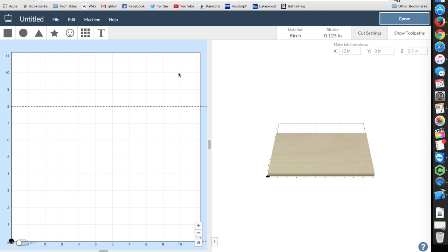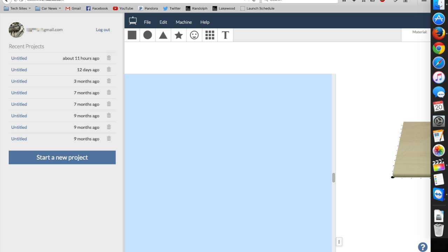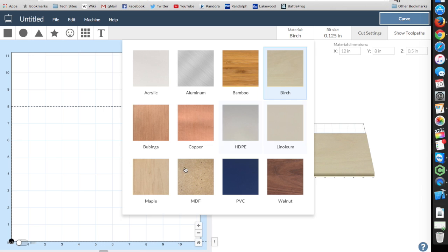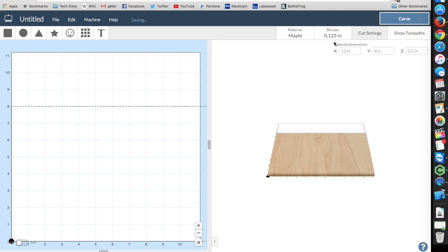Easel, for the uninitiated, is another browser-based solution created by Inventables back in the Shapeoko 2 days, and it's open to anyone with an Inventables account. It gives you the option to save your projects in their cloud and is optimized for GRBL-based CNC machines. To start off, go to the Materials menu and pick the closest material to what you're cutting. Stock size doesn't really matter assuming your design will fit, except for the thickness, which needs to be accurate. Click anywhere else to escape the dialog box.